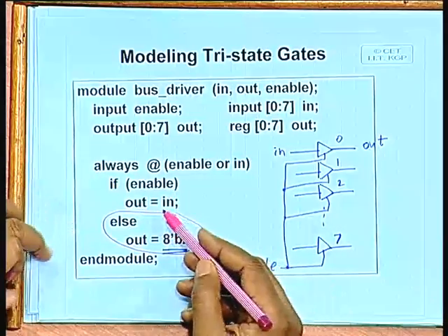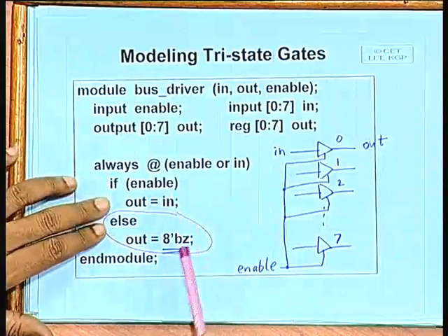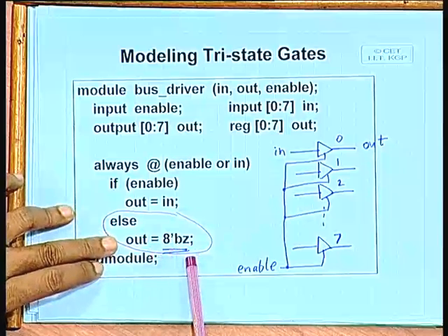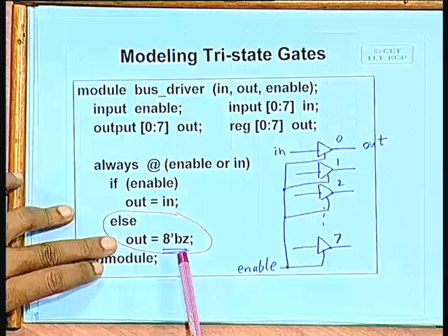So you have to remember the value. In that case, it is not a tri-state. You have to explicitly specify that under certain conditions the value will become Z. Then only will you have a tri-state logic family.